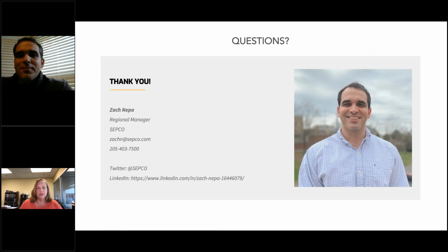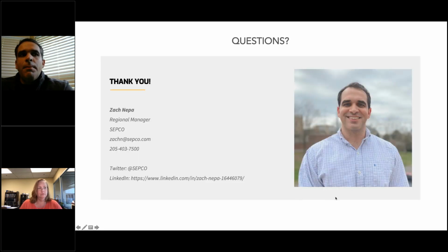We have a question that just came in. How hard is it to determine the proper amount of air, and what happens if too much air is applied? You're really not going to have much issue if too much air is applied. You might whistle a little bit more. You determine the air pressure requirement based on the head pressure of the product, and you just have to exceed the head pressure of the product.